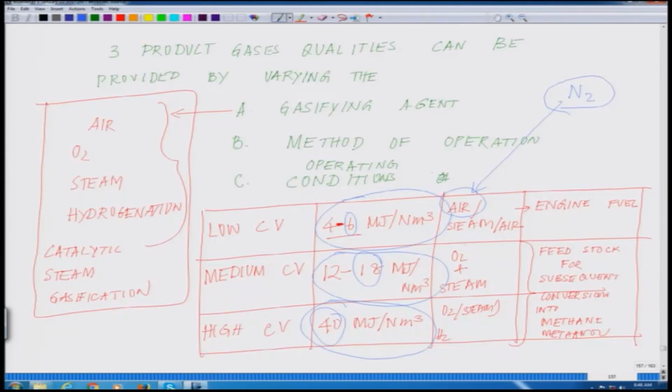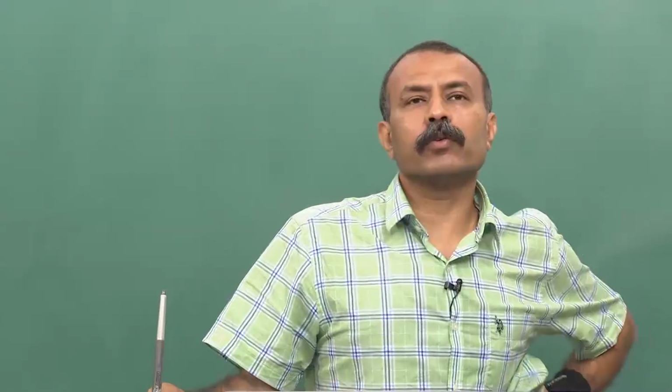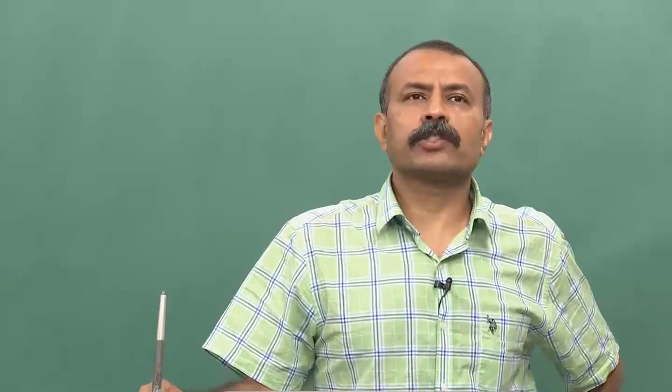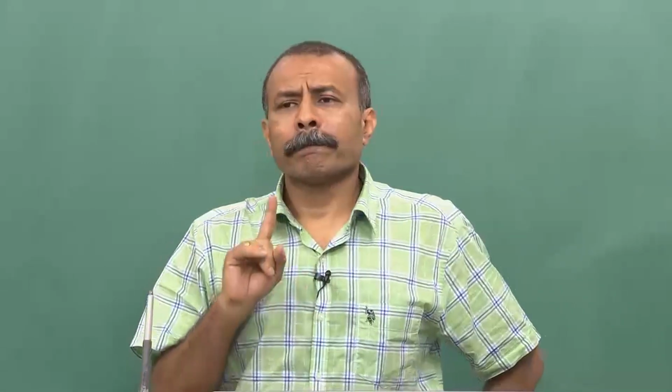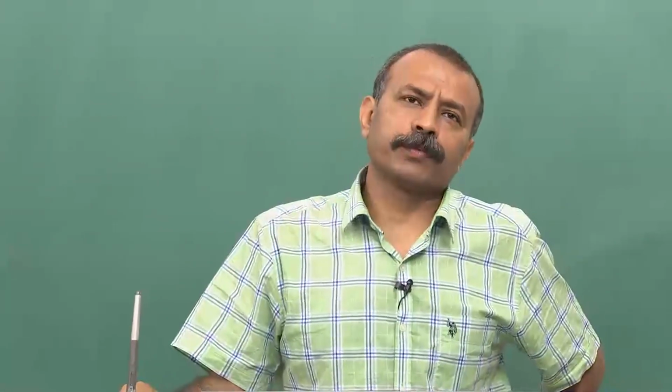Whereas, if you use pure oxygen, which is being used here, this is expensive. You have to have pure oxygen to do this reaction. This is not something very easy to do. And here you have another added feature: you are using hydrogen, which has also become expensive as well as a risky affair. You have to be very careful while dealing with hydrogen. You have every chance of a blast or something. Now, it is a kind of trade off.